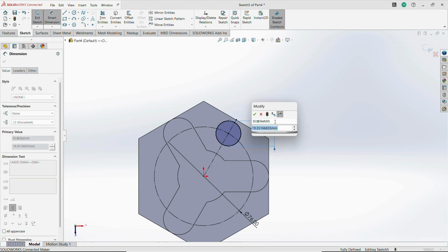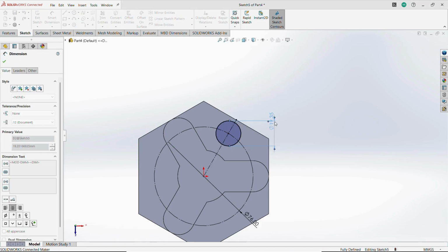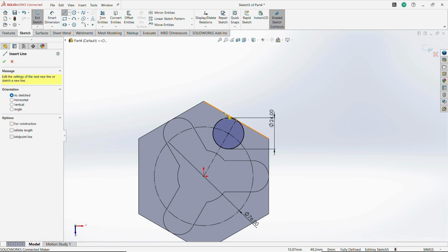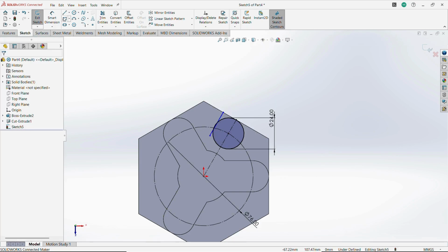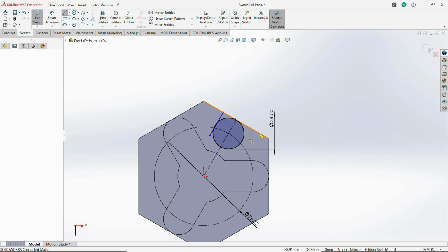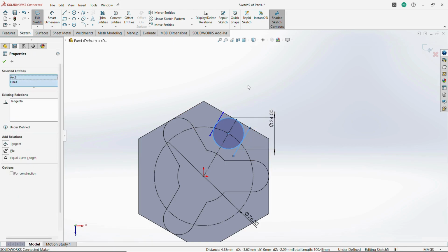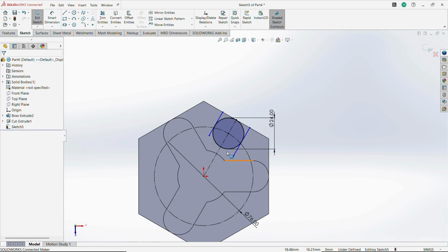Okay. Use the smart dimension. We just select and initiate the dimension value of 24 mm diameter. That is the radius of 12 mm. Then close this with the two opposite line profiles. Here also I do not prefer an offset edit because it can introduce some kind of error. That's why, if you want to avoid that, we need to create a new profile in this particular portion.